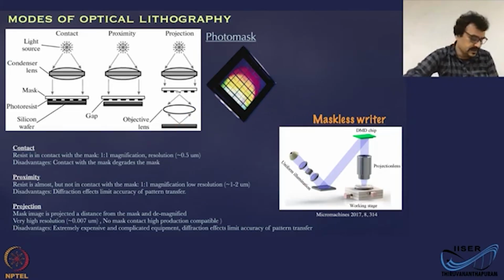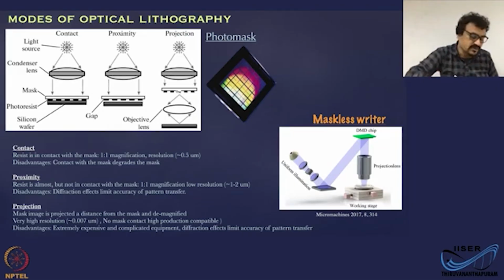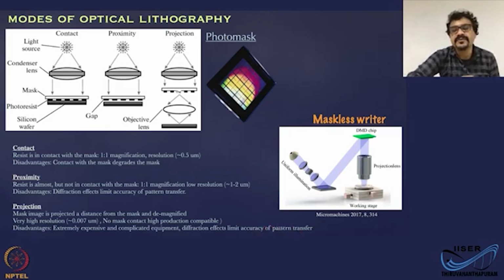Here you can actually get the resolution down to a few nanometers, and this is what is used in microfabrication in the industry. There is no contact with the mask, no mechanical alignment, no hard pressing or soft pressing of the mask with the material. So the mask is relatively pristine and clean, and you can have very high throughput using this method, but it's extremely expensive, and it's complicated equipment, and it's not really used in academic settings. This is mostly at the industry scale.